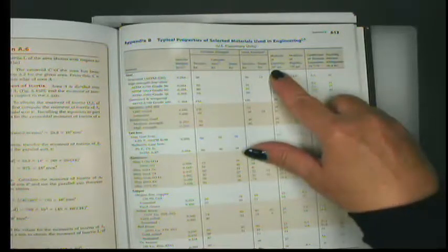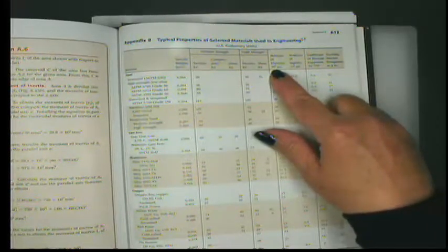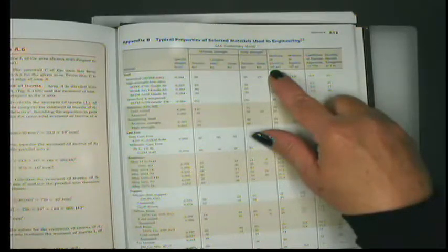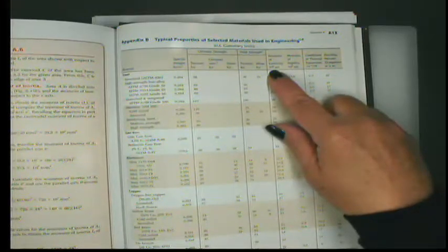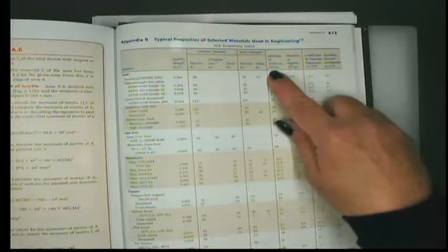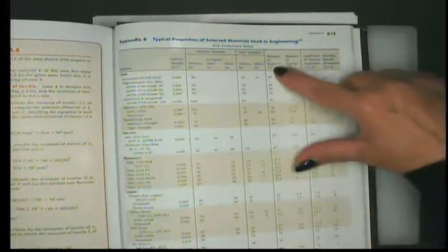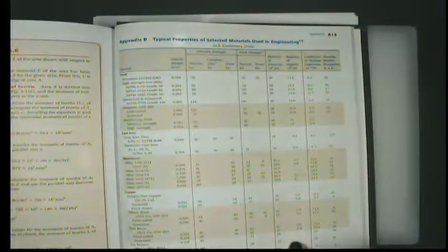And if we have units of psi, the modulus of elasticity is often a very huge number, because remember, the bigger the modulus of elasticity, the less stretchy a material is. So what that's really saying is that you have to put a lot of stress on a material to make it stretch at all, which makes sense because we don't design with silly putty, right? We design with steel, and we design with wood, and we design with cast iron. So the values are shown here. They tend to be 2 digits times 10 to the 6 psi.